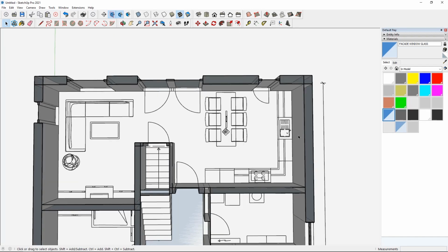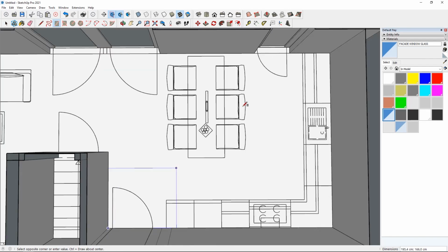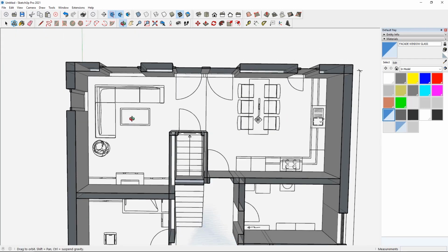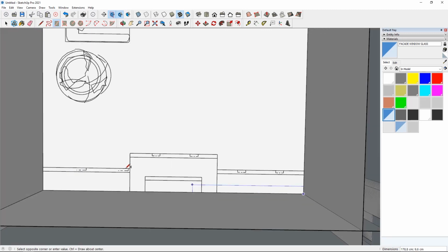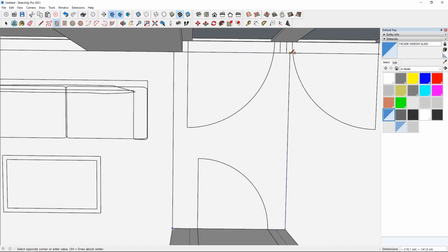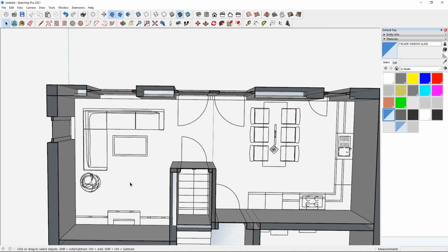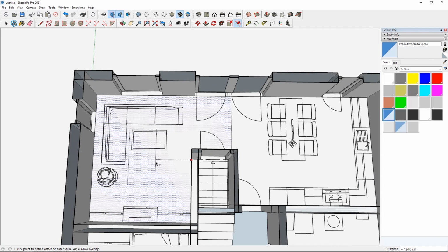For this bigger room, we can divide it into 2 zones, one for the kitchen dining room and another one for the living room. To create the zones, we first need to make a 50cm offset away from the walls. This 50cm gap will ensure a more precise daylight calculation.